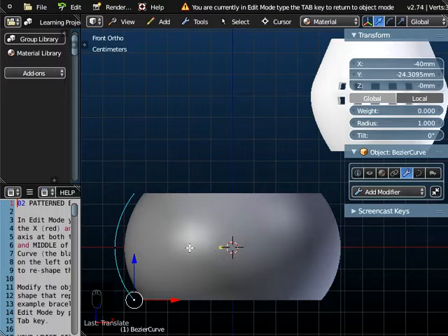The red line is the origin line, if you like. So when we're going down, it's minus. So you do need to make sure you put the minus in front of 25 millimeters. Minus 25 millimeters. That will locate it exactly at that point there. So that gives us our height of this object.